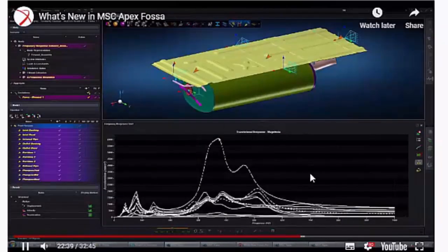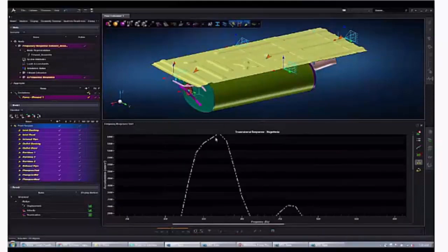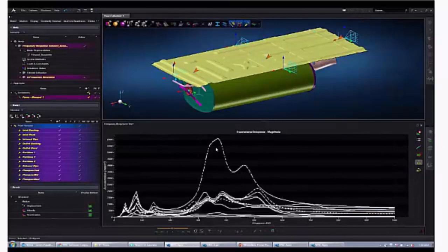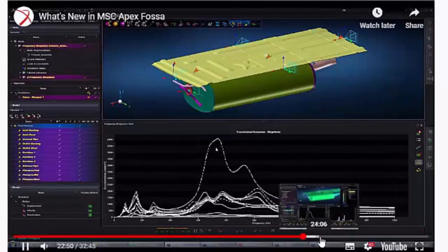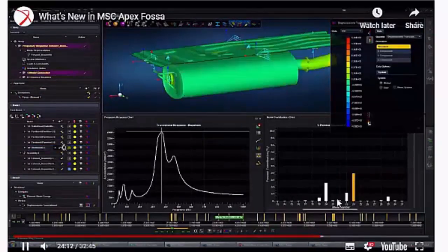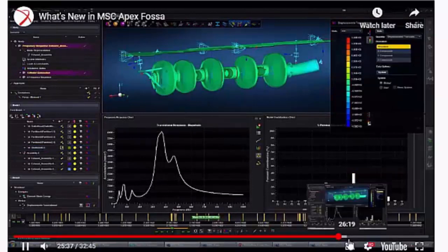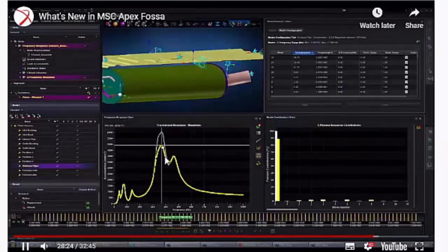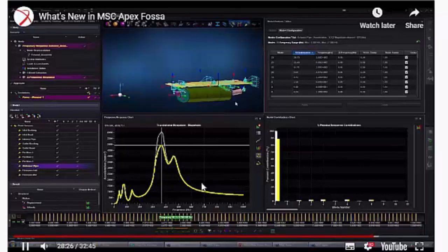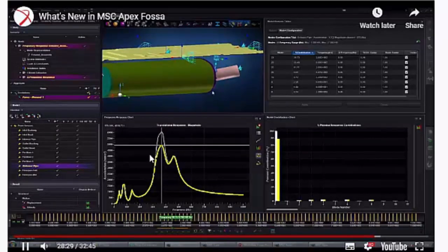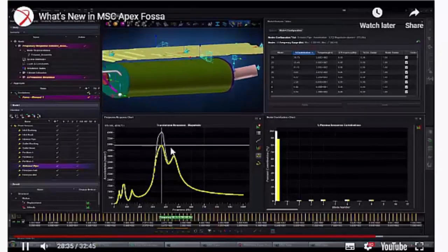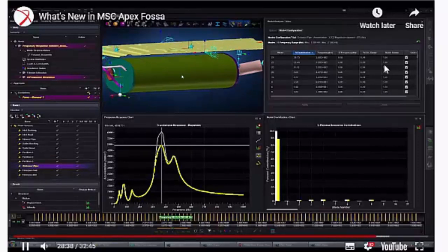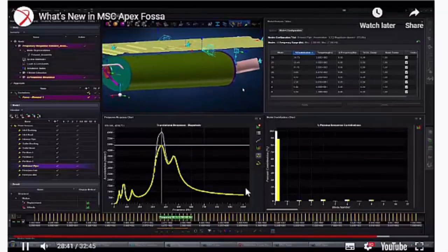And then you can interrogate the model and play what-if studies. So what if I were able to move the natural frequency of mode 7 by 30 hertz, and it can predict the result for you to say, this is what it predicts, how the frequency response would look. This is the point in the video where they now play this what-if scenario game, and you can see the predicted lower modal amplification, in this case for a particular shift in some of the input properties.